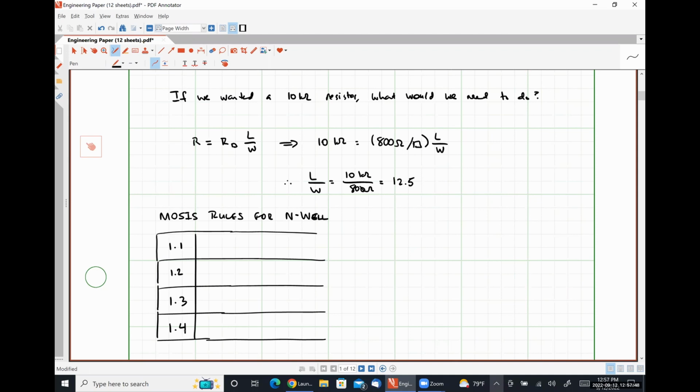The next one is probably TSMC, Taiwan Semiconductor Manufacturing Corporation. They have a 180 nanometer process node that a lot of people use. When this class first originated, around 4 years ago, we designed to the TSMC 180 nanometer process node. The lead time on getting those chips actually manufactured was about 26 weeks, which is the problem with the lab.